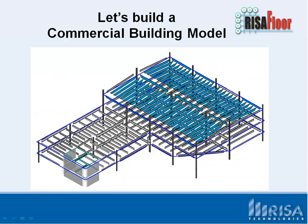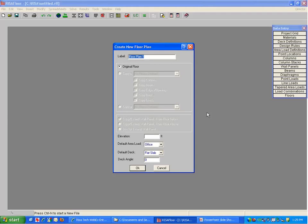So now that we've talked a lot about all the different pieces and features that we have in RISAFloor, let's build this model and see how we actually use those in practice. So I'm going to jump over to RISAFloor. In RISAFloor here, it's going to start out with a model. We're going to ask you to start with a floor level. So first floor, we're just going to title it first floor as a label.